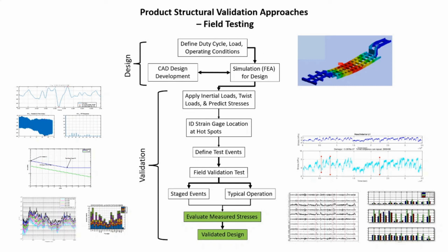One other thing that we may do is use the model to help us out a little bit. Let's say we could not locate a strain gauge in a particular area we are highly interested in, but we're able to get gauges nearby. We can use the model to give us some feeling of what the extrapolated or interpolated stress might be from our measurements. Sometimes this gets pretty complicated, but it's not always possible to locate a strain gauge in the particular location we're most interested in.